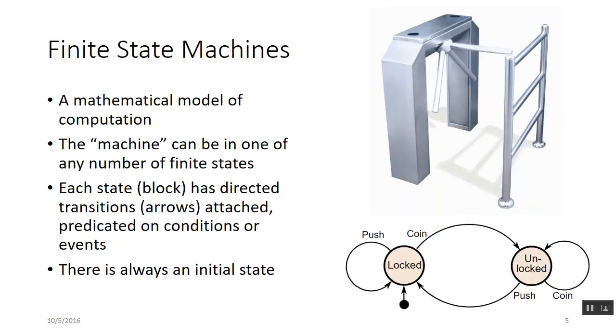I don't know if you're going to talk about this later, but how do you account in a state machine for if you're accumulating some value? Like, let's say that turnstile has some counter, that's the number of coins that are in, so that's the number of passes it will allow through before it locks up again. Right. We will get to that. There's basically in each state an action script that is what happens in that state, and you can write MATLAB code in there, and that can handle stuff like you're talking about.